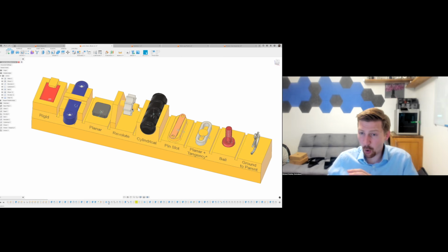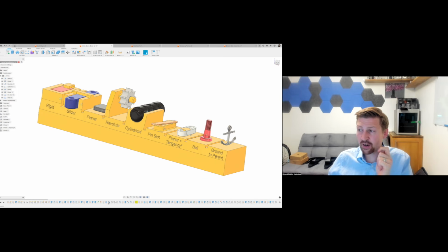Cylindrical has got 2. All of this, just think about as those 6 degrees of freedom and how many of them are free. You're defining its location and its rotation, or its degrees of freedom, with 2 clicks. It is brilliant and it is fast if the snap points are in the right place. So if I've got snap points at either the edges or the center points, it is perfect for me.